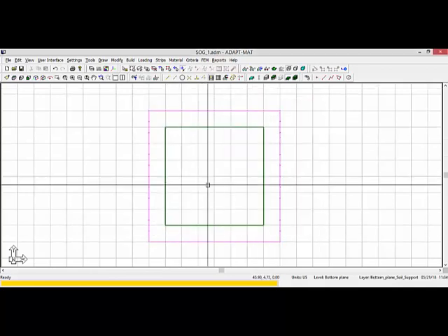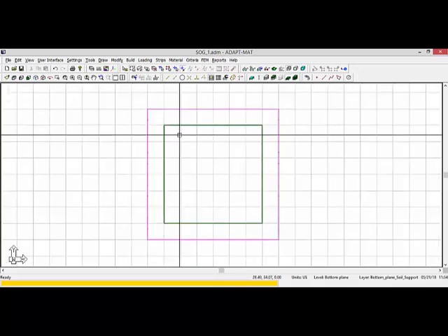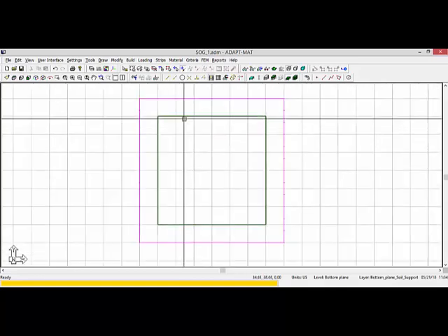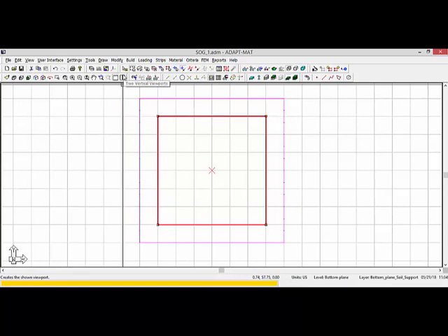We're now going to load the slab, so we want to make sure we have the loads on the slab that we want to perform an analysis for. So the first type of load that I'll model is going to be just a uniform live load. It just might be some load that we want to cover the slab with, just some baseline load for live load. We'll go ahead and select the slab, and if we go to loading load case library, we can see